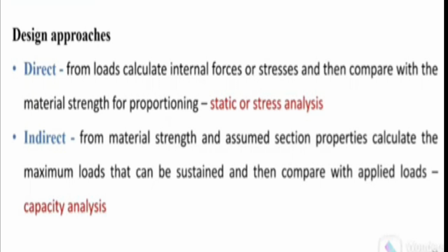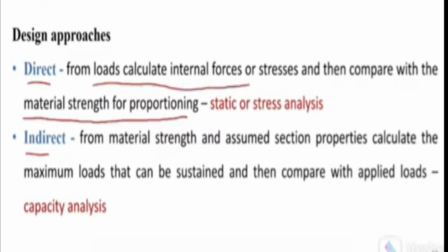So there are two design approaches which are mainly used. The first approach is termed the direct approach and the second is the indirect approach. In the direct approach, we calculate internal forces from the load, meaning we perform the static analysis, and then compare with the material strength for proportioning. So from load, calculate the internal forces and then compare with the material strength for proportioning.